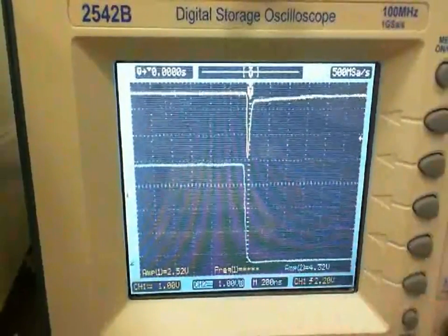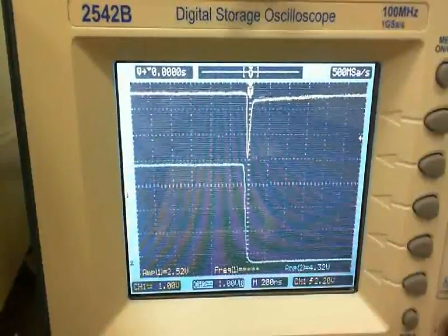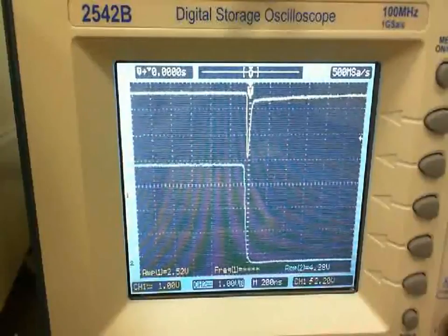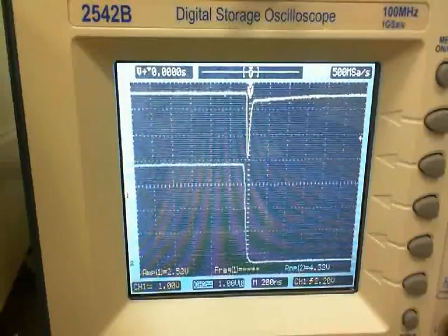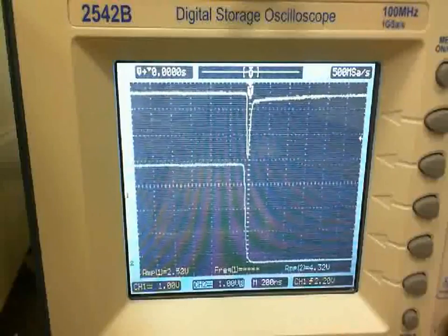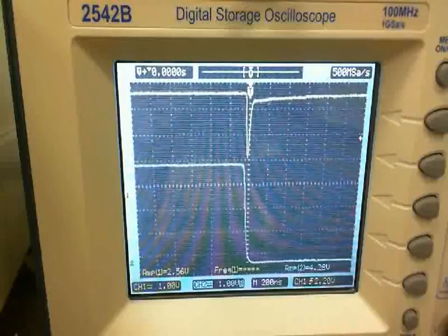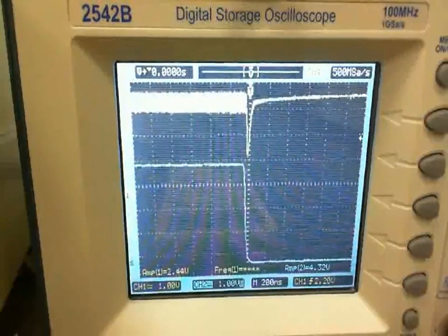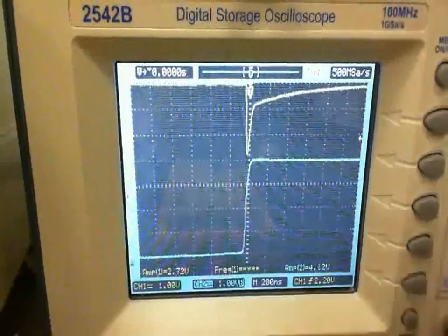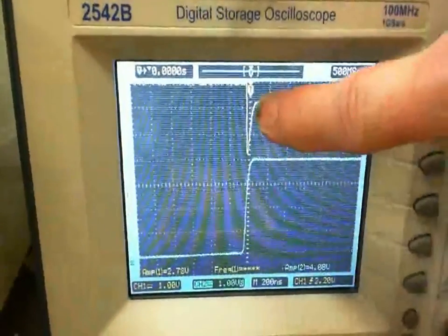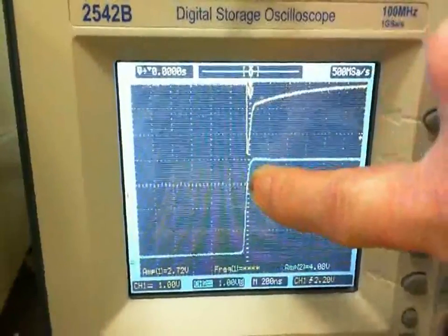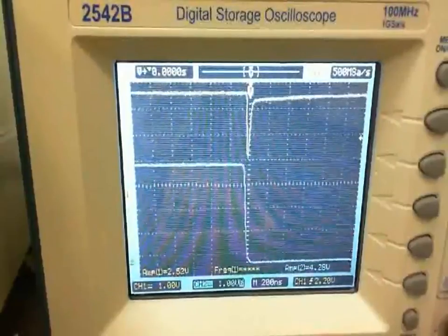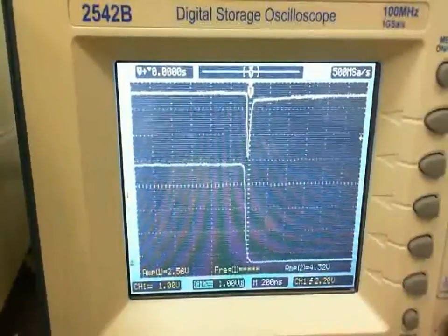So what I'm saying is that we can use this little circuit for what we call an edge detector circuit, which would give me an indication every time I have either a rising edge or a falling edge, depending on whether I use ORs or whether I use ANDs. If I use an AND, then I have what we call a rising edge detector. See, so this is the pulse output of the circuit. Here's that rising edge. If I use an OR, then here's the output of the OR circuit, and then I get a falling edge detector.